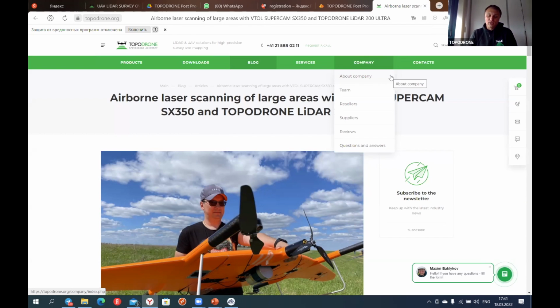In this case, for a power line survey, I would definitely suggest using both solutions, LiDAR and photogrammetry. Also, if I can mention, it's quite hard to get the tower with photogrammetry, and it's almost impossible to get the ground, especially if it's below the vegetation. So this is the main difference.